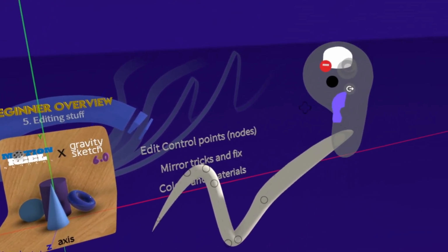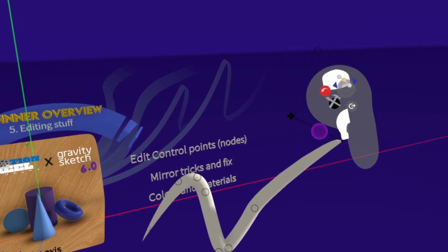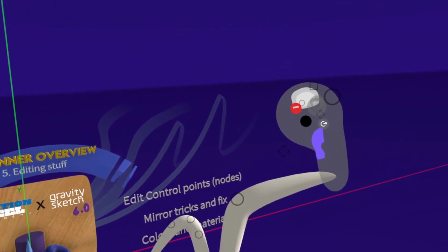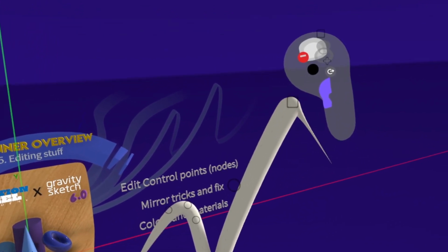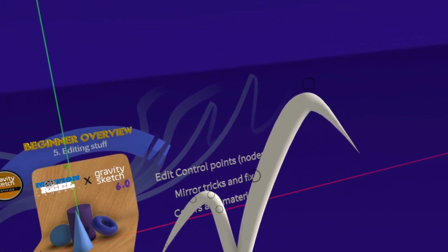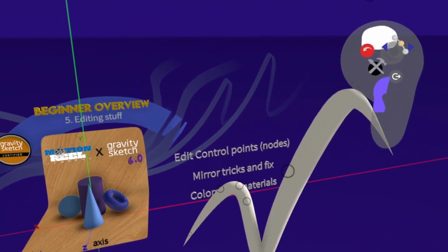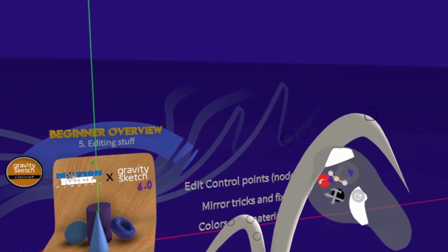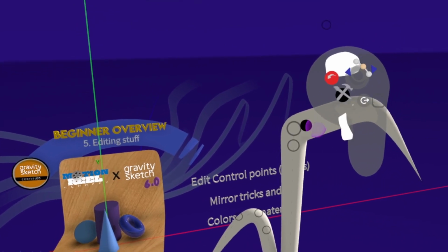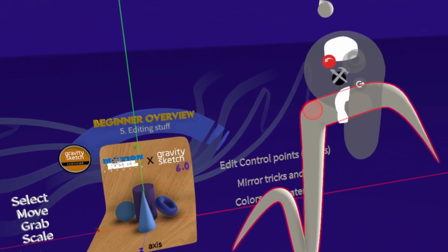So you can do all kinds of different lines and combinations by making things thicker and then changing its line style to create all kinds of different lines. Now that's one way to do it. You can also do it by putting multiple points. If you want to make a corner or a hard corner, you need 3 points. So we'll add 3 points here. And now if I move these close together, you'll see now that I have a hard corner here as well.